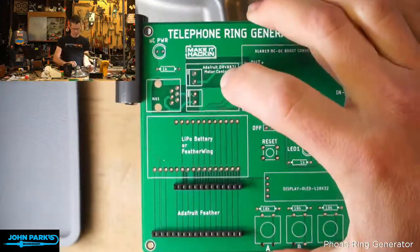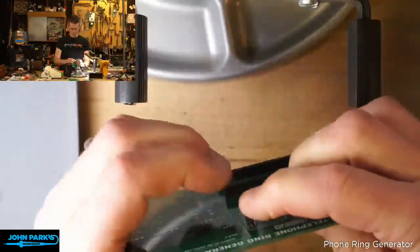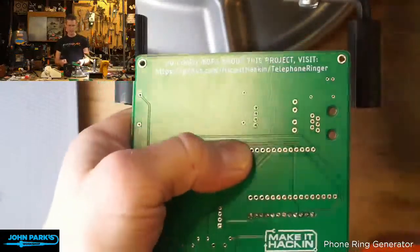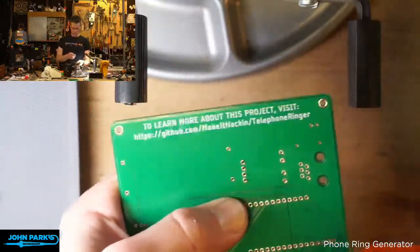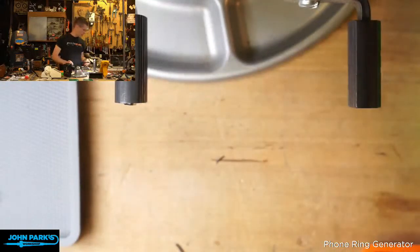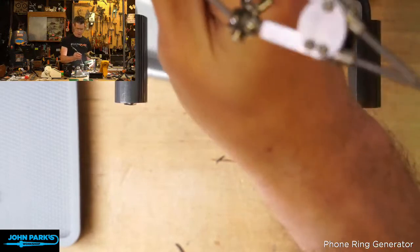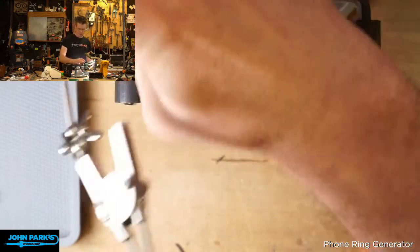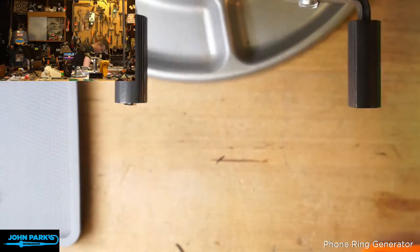So in a case like this, you can tape these down. You can use some blue tack. You can use a rubber band. I like to often just hold it with my finger and then try to solder the first one in place with the solder wrapped around a little holder. So let's see, I'll use this one. I have a magnetic base on this. Let me find something strong enough to hold it up. There we go.